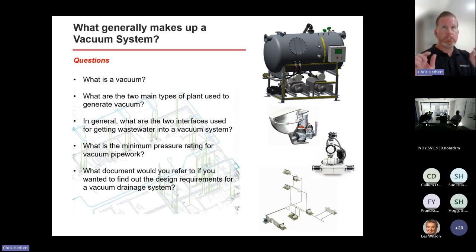But yes, it's generally for that initial 3-meter lift from the toilet to move the waste vertically. We reduce the pipe size and we increase the velocity for, say, Costco, for example. We'd have a 25 mil riser pipe, and that we can lift 7 to 8 meters. Really, 10 meters is kind of the maximum in terms of liquid slug. 10 meters is 1 bar, the complete differential between sea level and absolute zero space. But yes, it's a good question.